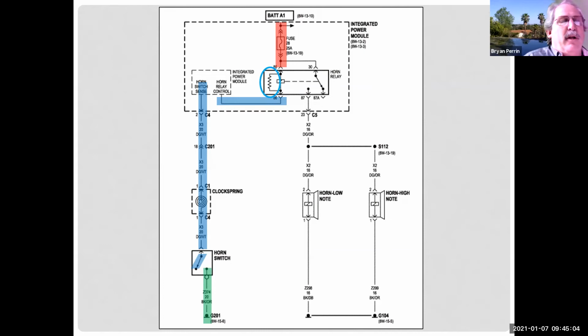And that's the power of looking at wiring schematics. If I have multiple systems that aren't working, the question is, do they share a power or a ground? So, you know, if they're related systems, they may share power. They may share this 25 amp fuse. And I could go to power distribution schematics and see everybody who uses the fuse. I could also go to my ground distribution schematics and see everybody who uses G104. And so very quickly I can figure out, wait a minute, if everybody that uses G104 is what the customer's complaining about, it makes sense to go test G104, right?